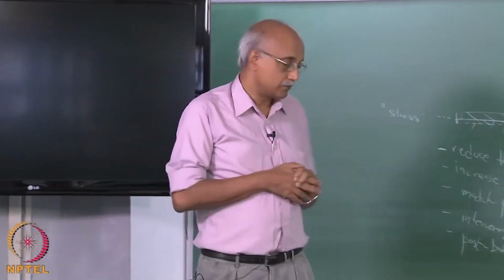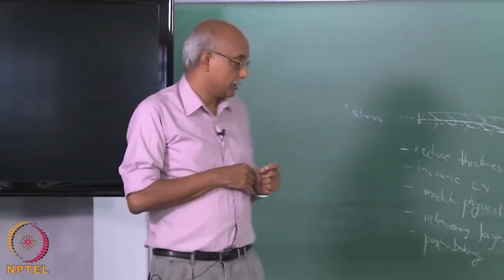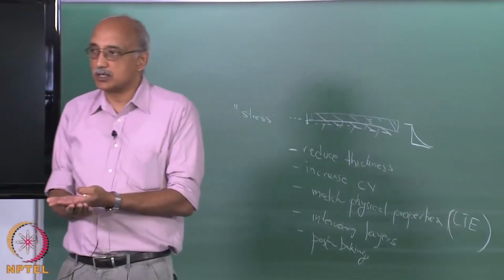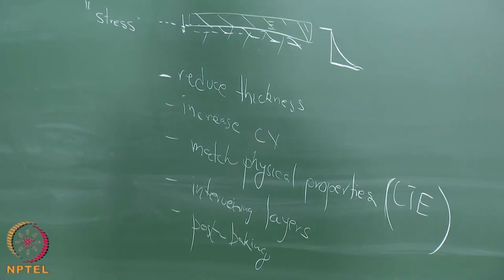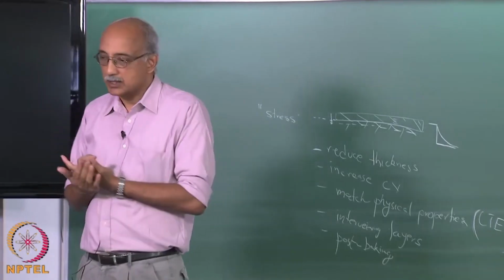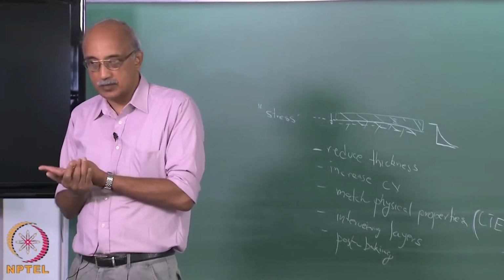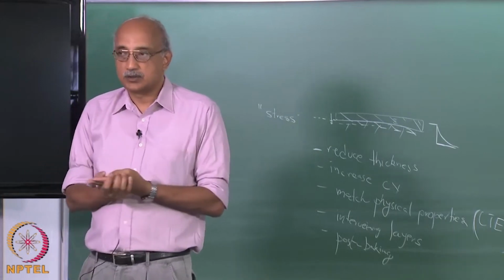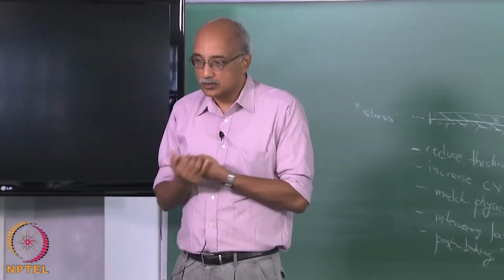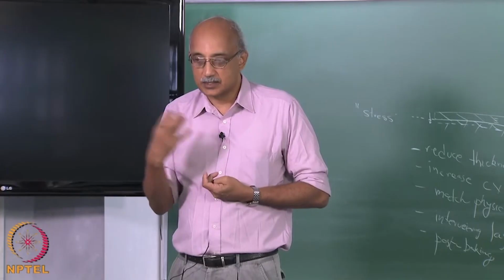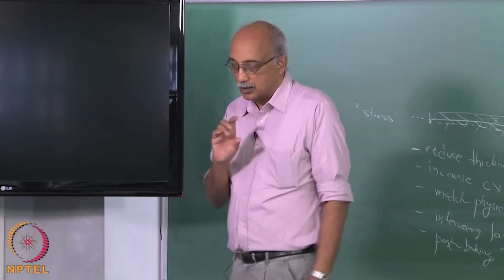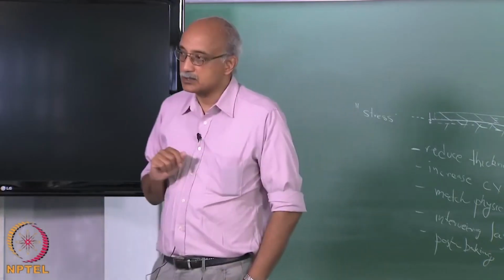So, matching the structure is also important, and that can be done by post processing. For example, if you have an amorphous substrate and you are trying to bond an amorphous film, you probably do not require a post baking. However, if you have a substrate that is rigid and a film that is amorphous, that is okay for time 0 to get adhesion to happen, but then once the film is bonded to the surface, you want to control its structure to provide the necessary physical properties. So, you can resort to things like annealing in order to improve the properties of the CVD coating.